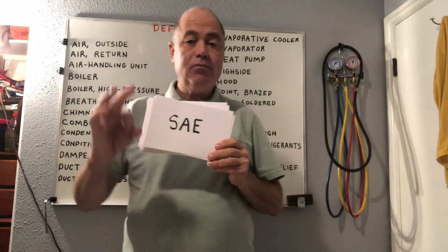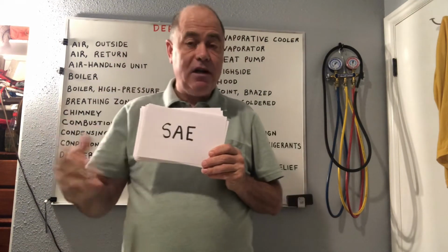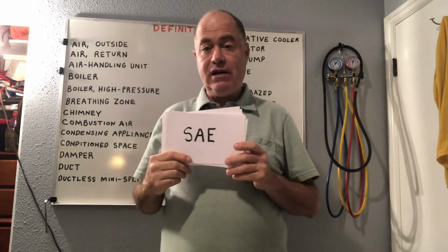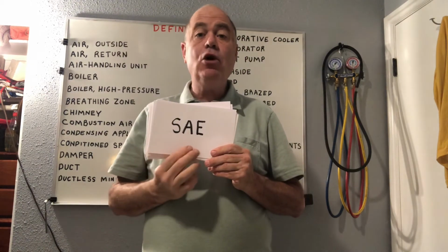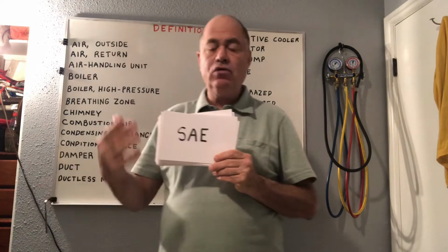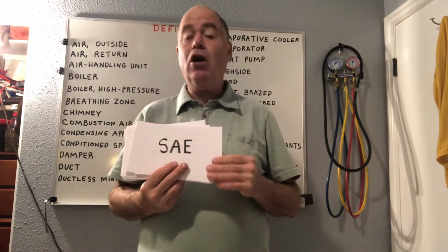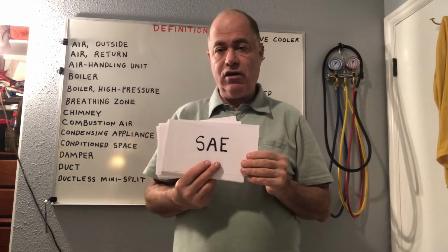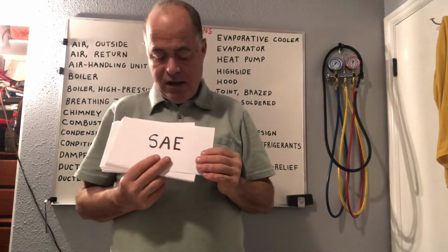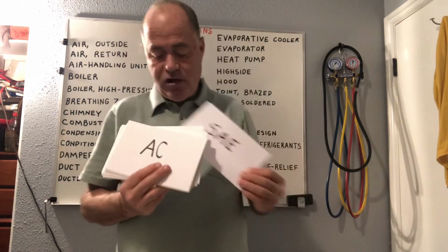Okay. This is SAE. This is how we abbreviate a flare connection to make a mechanical flare connection in our trade. And it stands for Society of Automotive Engineers, because back in 1910 or so, they were invented and primarily used on cars, and then they made their way into air conditioning and refrigeration. SAE for flare connection, Society of Automotive Engineers.